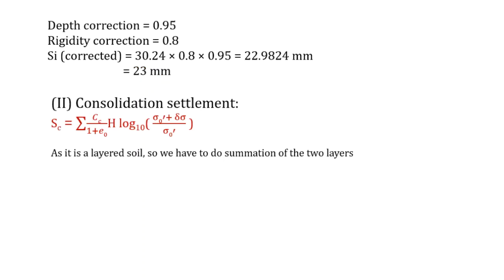Now this is the formula to find out consolidation settlement. I hope we already know the formula, but in this case, since it is a layered soil, we have to do summation of the two layers.